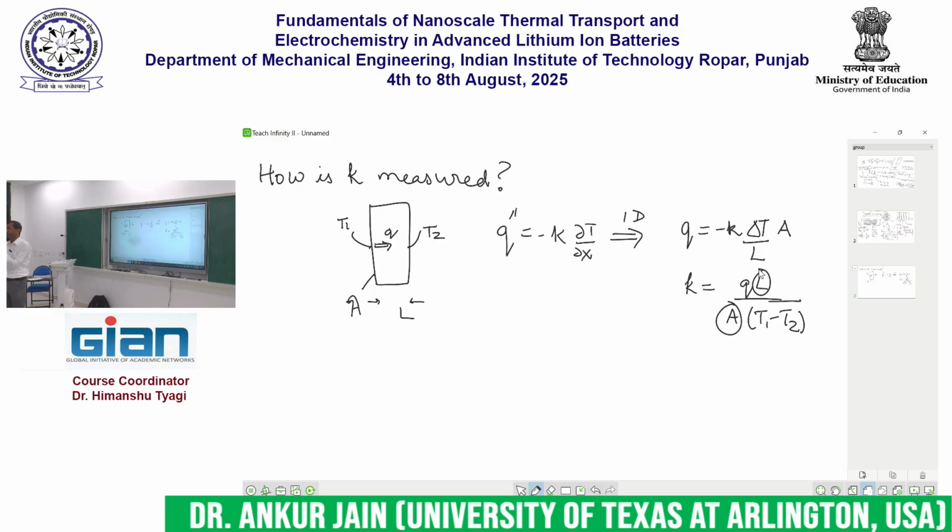Or alternately, if I can force a certain amount of heat to flow across it and measure the temperature difference caused by that heat flow, then I'm good as well. You see what I'm saying? So in other words, in order to measure the thermal conductivity of this lithium-ion cell, I need to hold it like this. I need to somehow make some heat flow through this and leave from the other side, and then figure out how hot it gets on the hot side compared to the cold side. Any ideas on how I can force some heat to flow across my cell?